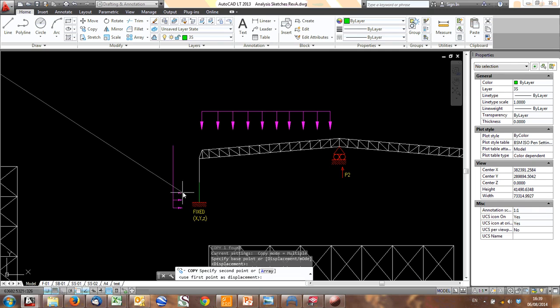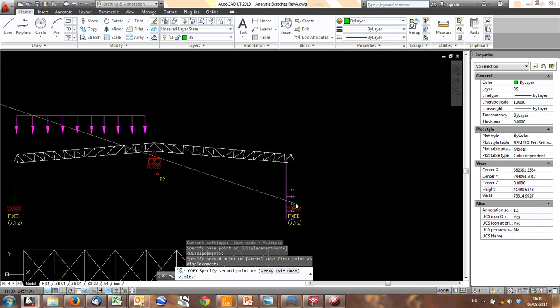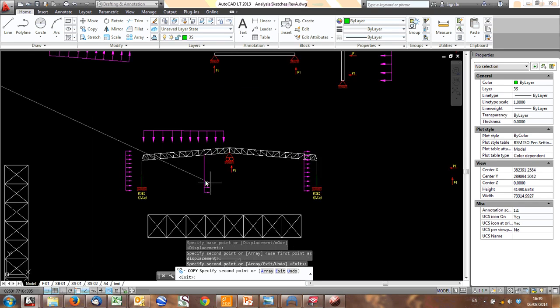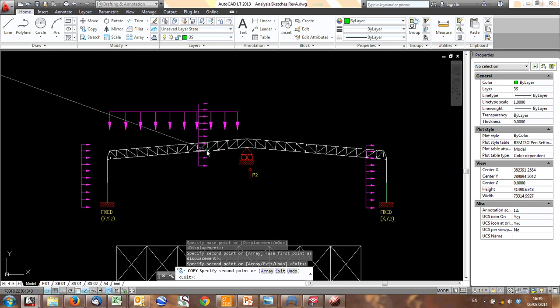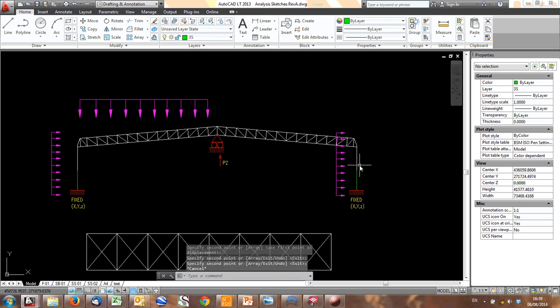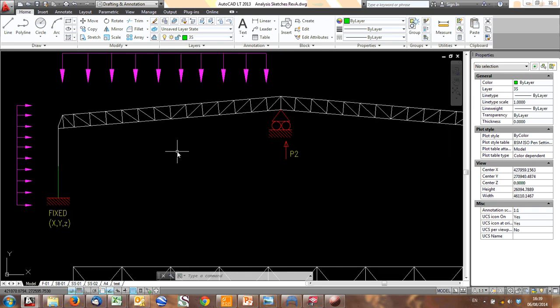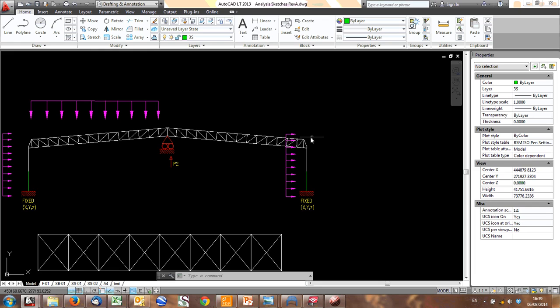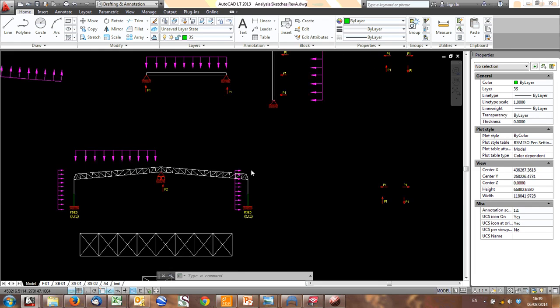You push this structure across because there'll be wind load here. There'll also be suction load on this side, so you'll be pushing across, pushing across. At the same time, you'll have uplift wind pressures or possibly downward wind pressures on the roof. So this is all pushing across. You need to stabilize it. You could design these concrete columns shown in green to carry the load. Or what you do is you stabilize it using roof bracing.